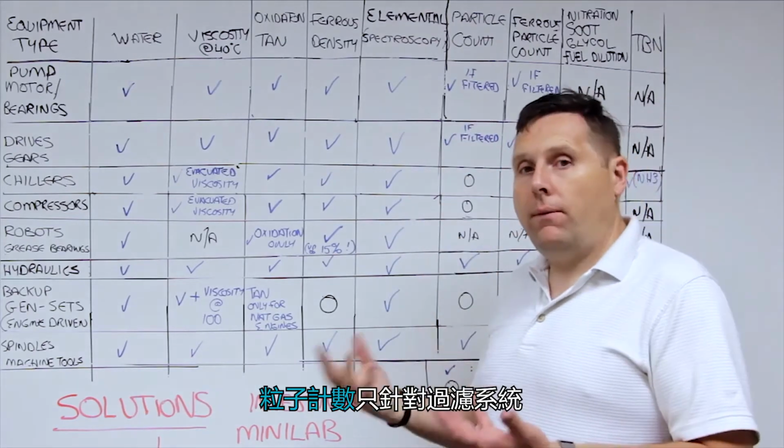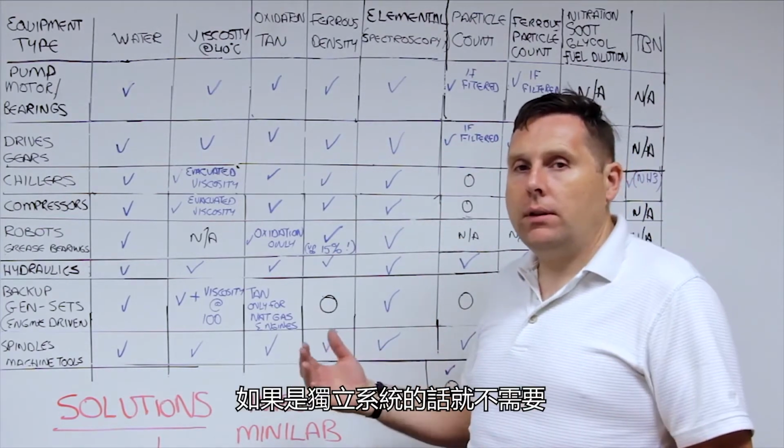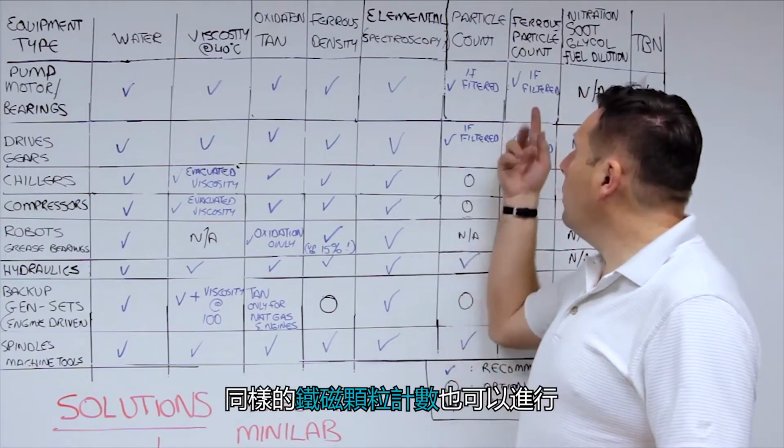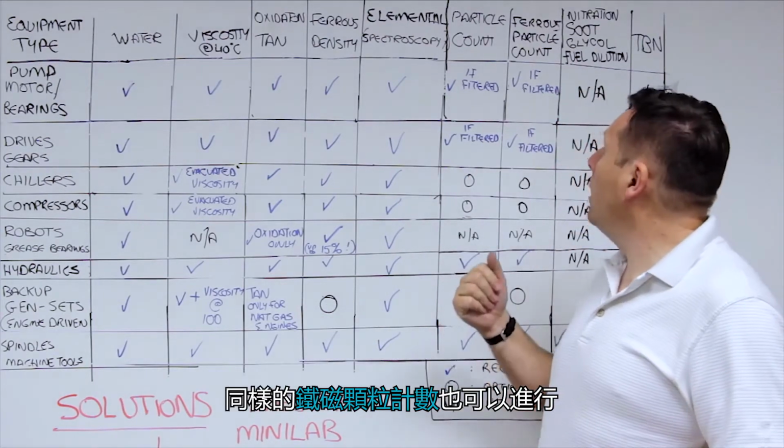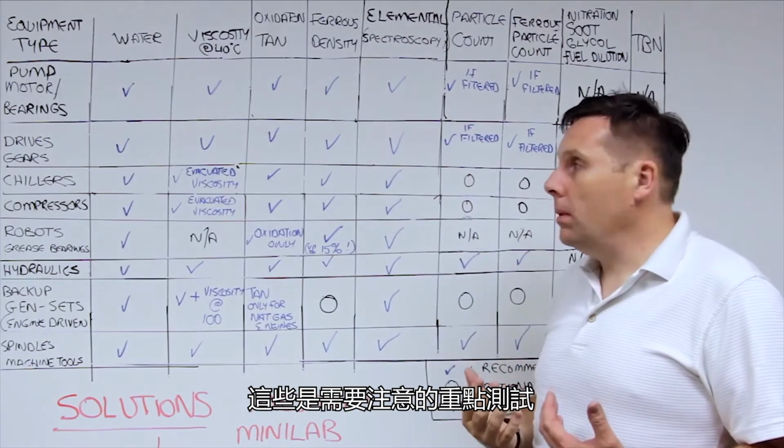Particle count, only if it's a filtered system. If it's a self-contained system, it's not worth it. Likewise, with ferrous particle count, and those are the key tests that you want to be watching for.